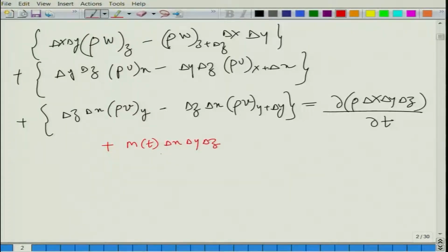So, why did we multiply here? This plus term is of course there because now we are assuming some sort of source term, and this m dot delta t is really the mass, as a function of time, that is being injected or taken out of the system, or this elemental cube. The m dot tells you that this is per unit volume, so you just have to multiply by the entire differential volume, the small elemental volume, to get the total mass that is being injected or taken out over the small elemental volume.